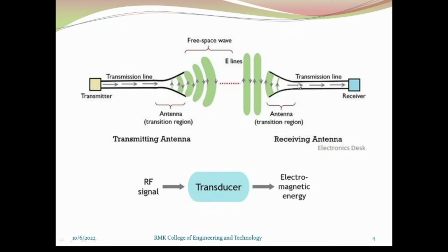So now this is the clear diagram of the antenna radiation in free space. This is the transmitter and transmission line. The signal is transmitted over here, then it forms the electromagnetic signal. Up to this point, to some extent, the wave is spherical, and then this is the plane wavefront. The plane wavefront will be the perfect transmission of electromagnetic signal in free space, where the impedance will be properly matched with the free space impedance, right?